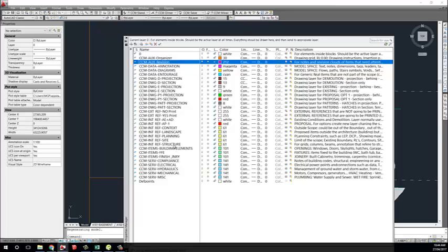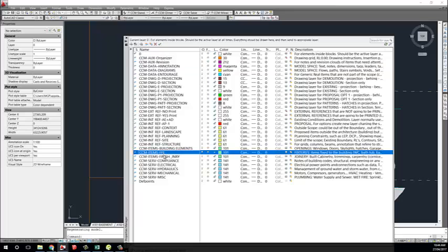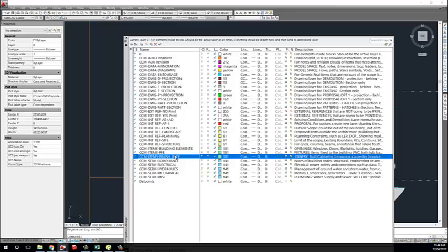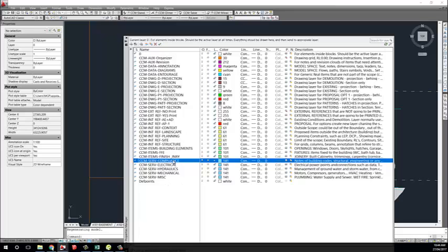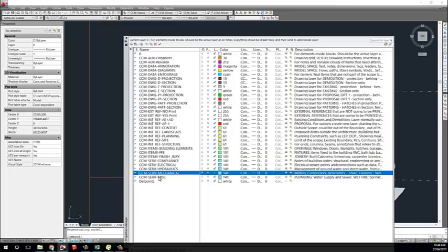And then structure, normally the grid lines, and then we have items. So we have built-in elements such as windows, balustrades, stairs, things like that we need to annotate. FFE, that comes from furniture, fixtures, and equipment, so things that we can move. Finishes and joinery, so the final layer of anything. And then we have compliance in construction, like normally specifications, electrical, hydraulic, mechanical, and then miscellaneous, because there are many other things we can do, but are not that common, so we can check everything in miscellaneous.